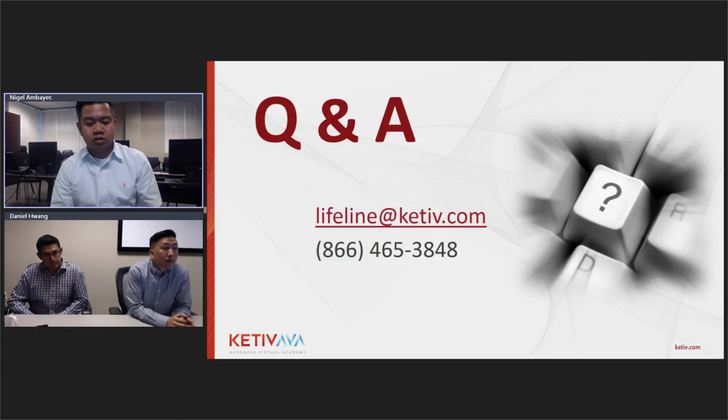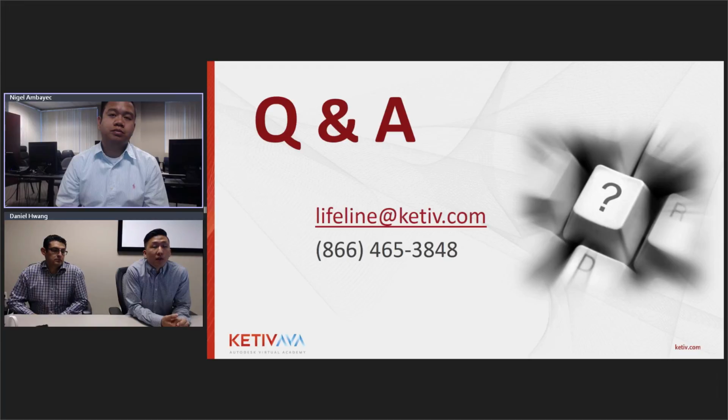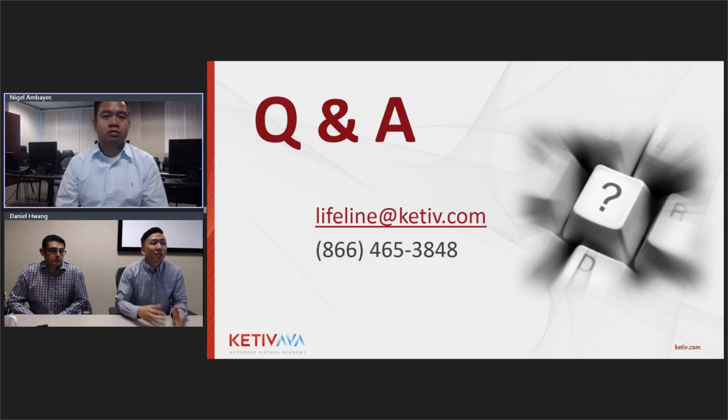Okay. And then this one comes from Jose. If you have a styles template, but you don't have a shared network drive, how do you share those style changes with other people? I think what you can do is save those to a template. So save them locally, and then share that template, and then you can save to the library as you share the template. So each person would have to go to their Manage tab, their Styles editor, and then save each local change to their style library, selecting all the options, yes to all, save. That way all of them have the same library then.